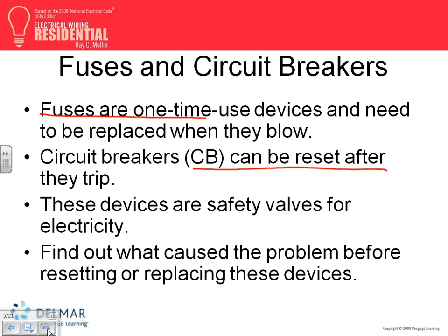Engineering-wise, a lot of engineers go for circuit breakers. Circuit breakers are intelligent devices. You can talk to them, pull information from them. Fuses are dumb devices. One-time deal, they cut it, and it's over. You replace it. That's a disadvantage of fuses: they do one job, one time. They don't live to fight another battle, and they're not intelligent, where you can talk to them at a level of 2,000 amps and higher.